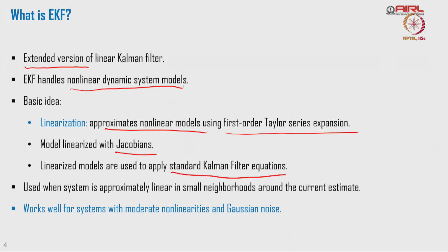Okay. So, most of the steps in the EKF algorithm resemble the Kalman filter algorithm as well, but there are certain differences. When it is a nonlinear model, then first you have to linearize it by Jacobians. We do it by first order Taylor series expansion, and then we get the model and use it in the algorithm.